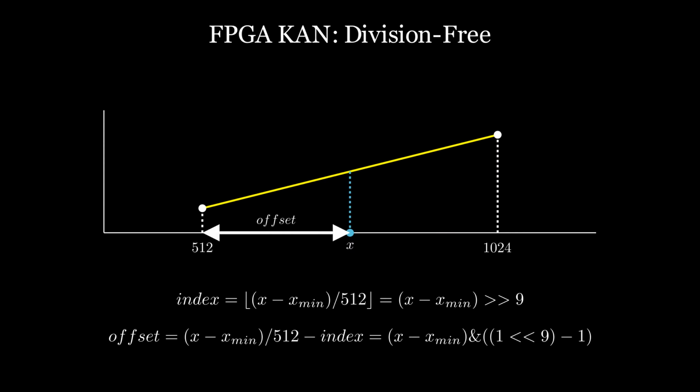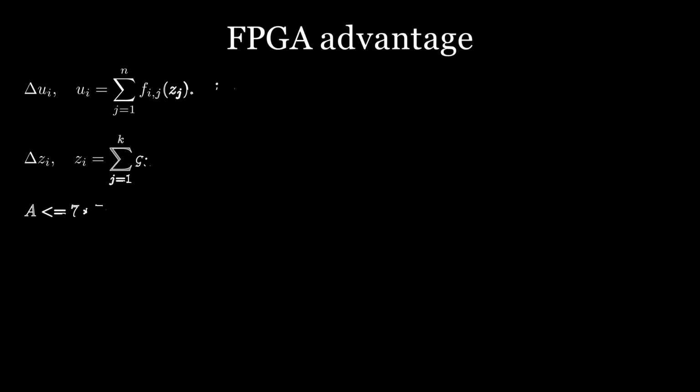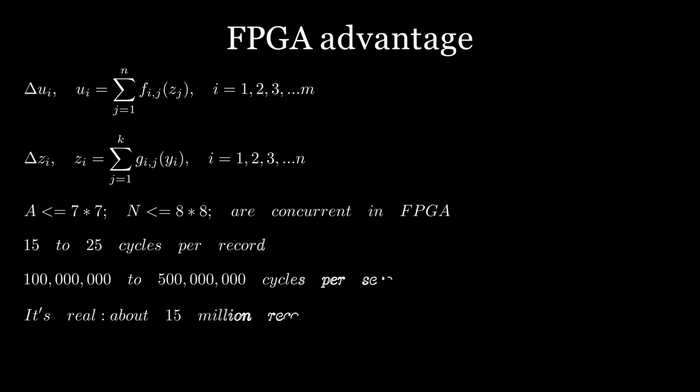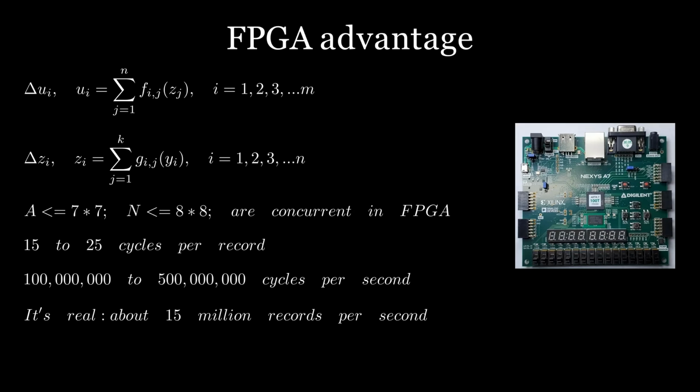Another convenient property of FPGA hardware is the support for arbitrary integer bit widths. Values do not need to be restricted to 32-bit or 64-bit representations. Instead, bit widths can be chosen freely to ensure numerical stability, for example 13, 17, 47 bits, and so on. The image below shows a simple FPGA board used for a prototype implementation. Its cost is only a few hundred dollars, and it is suitable for testing purposes rather than production deployment.